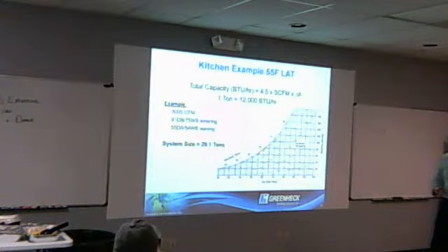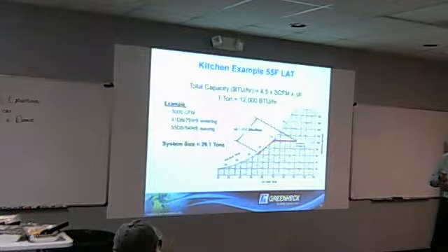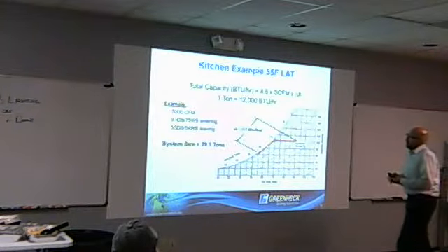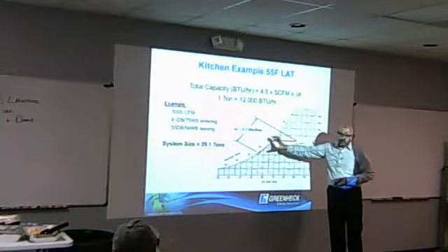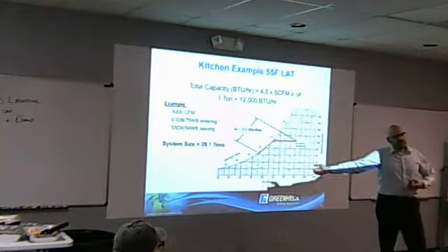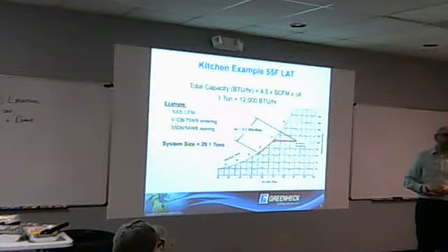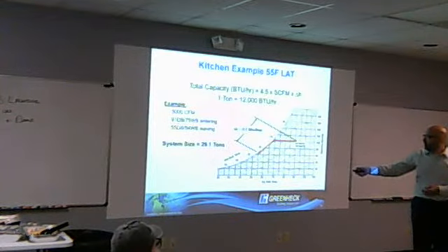So that's with the DOAS unit, not a makeup air. That's correct. Makeup air would be even higher because you don't have the energy recovery. Makeup air, yes, right. So whatever gets us to these conditions, whether it be with or without a wheel, it's just to show the difference in capacity of taking it to 55.